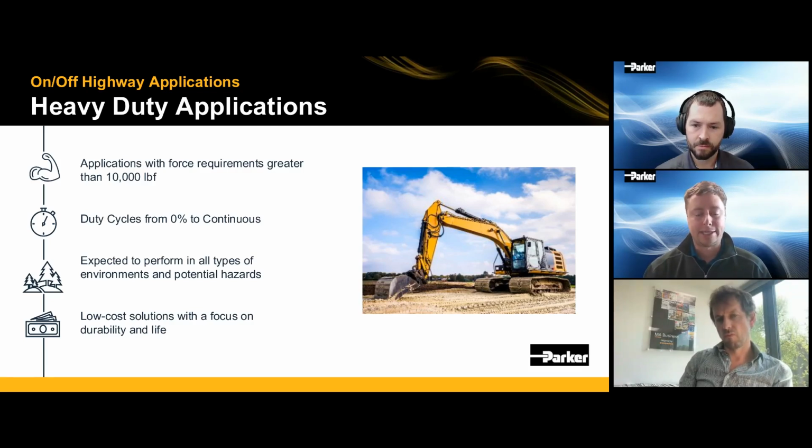But once it gets to that inflection point, where both the speed rapidly decays and the life rapidly decays, the efficiency also takes a huge hit. That's really where we get that fluid power density in hydraulics. So through our own testing, we have seen an efficiency gain between that 2,400 to what we tested up to about 5,000 pounds of force. We've seen that we are 3 to 5% more efficient. So that's 3 to 5% less amp draw. That's great. Great questions.